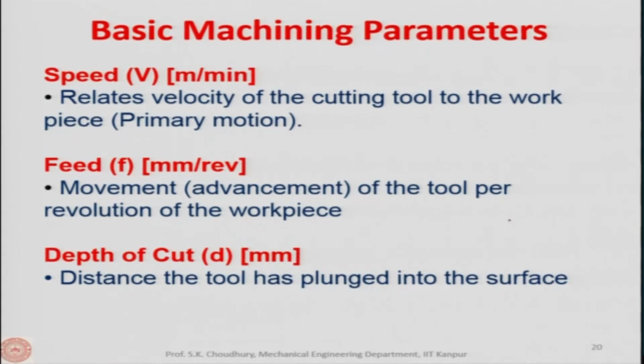surface. Okay. So, for example, if we have a part like this, and this has been machined like this, let us say, this is a cylindrical job, this is the tool, let us say it is a turning process. Now, this is the cutting velocity which is provided to the workpiece, and this is the feed motion or the feed F, this is the direction of the feed which is given to the tool, all right.